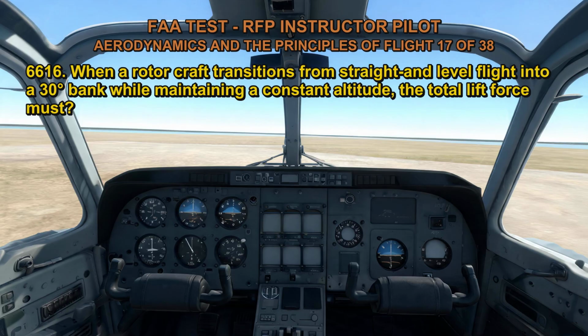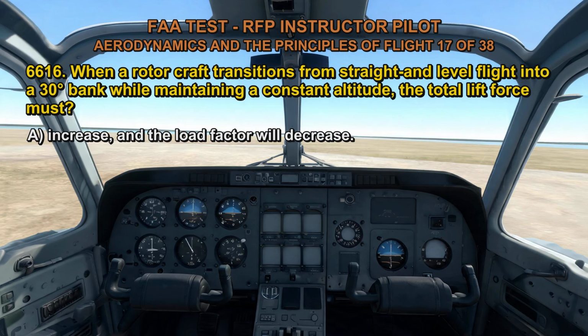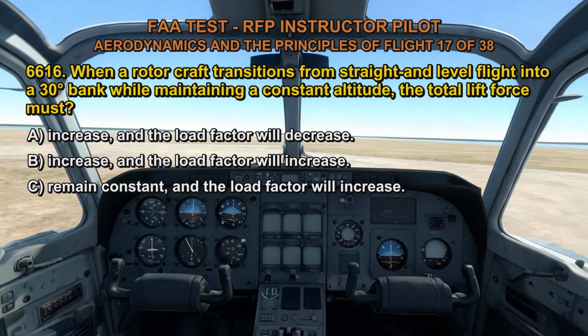6616. When a rotorcraft transitions from straight and level flight into a 30 degrees bank while maintaining a constant altitude, the total lift force must: A. Increase, and the load factor will decrease. B. Increase, and the load factor will increase. C. Remain constant, and the load factor will increase.